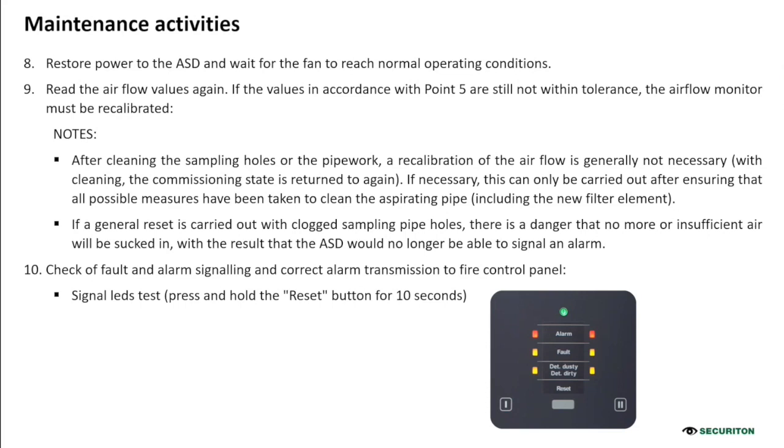When you make this operation, it is very important to be sure that the pipe and the holes are properly cleaned up, because, for example, if you perform this initial reset without doing the proper maintenance, you could reduce the performance of the detector, because what is important is to restore the nominal airflow value.